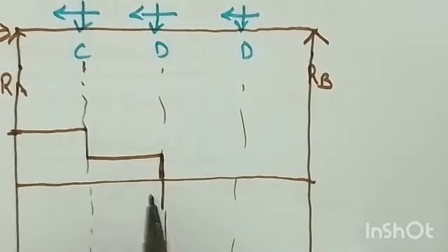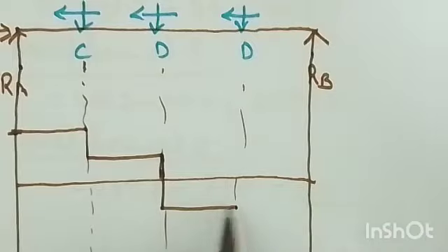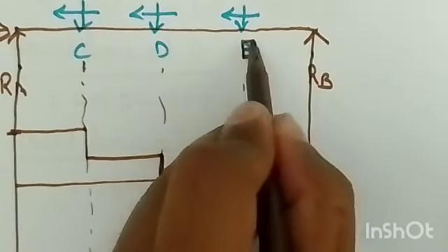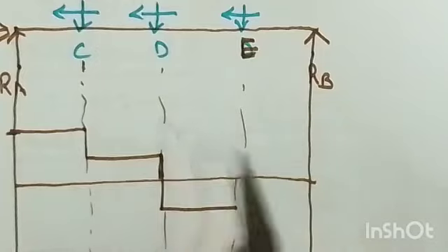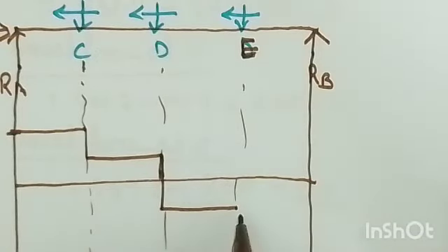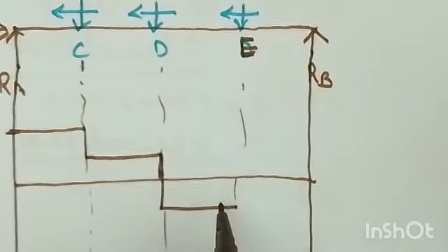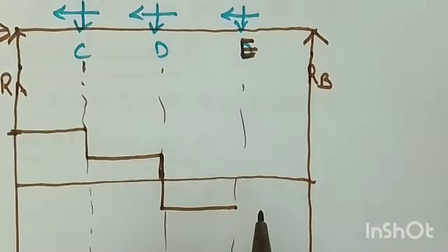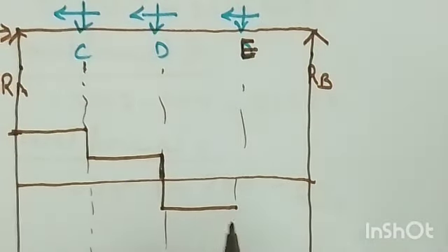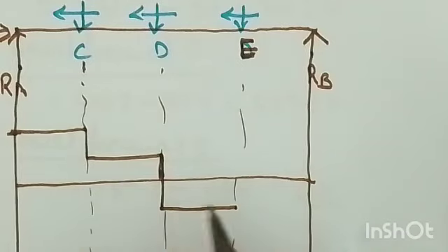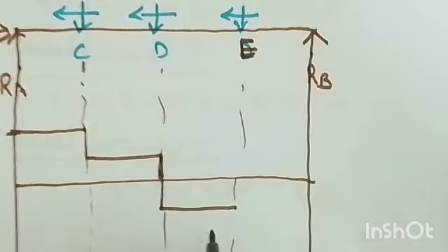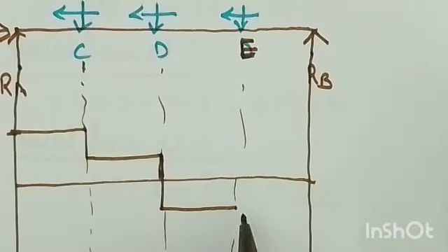It will come down and remain constant between D and E, right. So these are the little mistakes which we can make. Now at E the shear force becomes what? The shear force remains constant between E and B, and the shear force at B is 204.85, right. So this is your 204.85, so it will be added by this much and then it is like this, right.